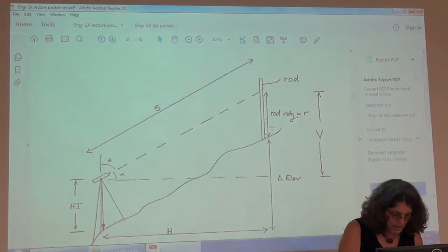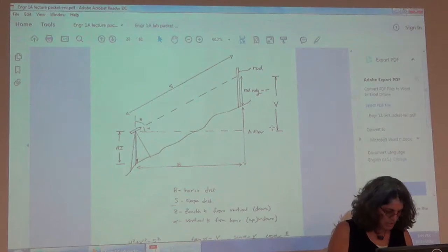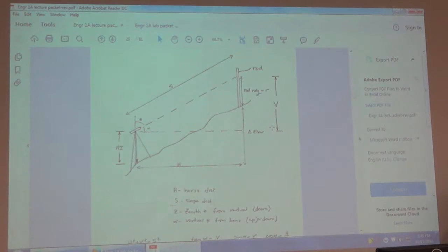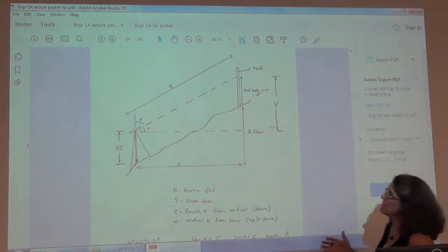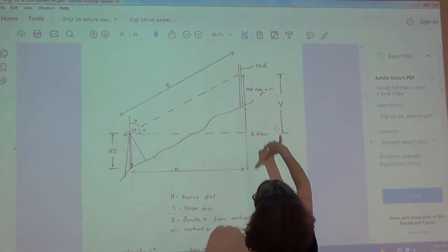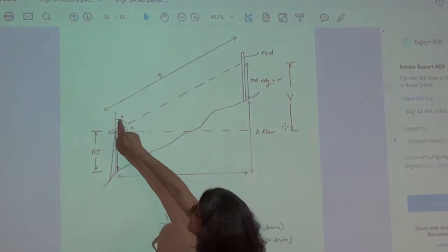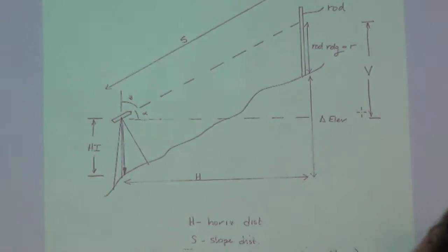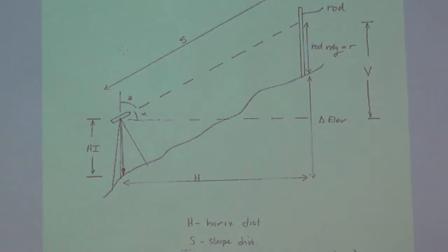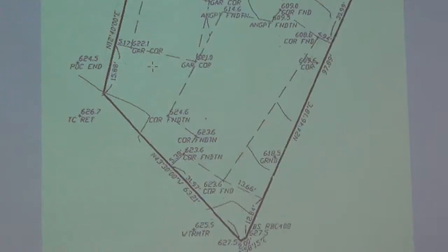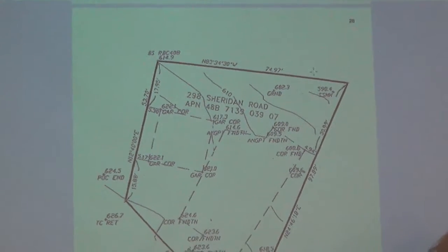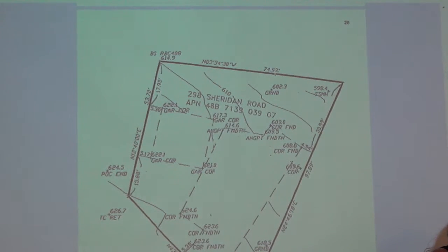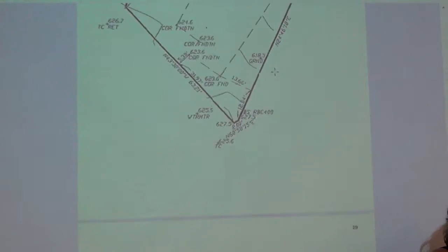But this question is it's still in this material, isn't it? For the total station lab that you're going to do where it's the height of the tree, you're looking at this kind of stuff. You have a horizontal distance, you have some vertical measurements, you have a slope distance, you have what angle is that? Zenith, you have a vertical angle, and be able to calculate stuff. You need to be able to see all this. Now when you're representing a boundary line, it's got to be bearing and distance. What kind of distance? Horizontal distance.